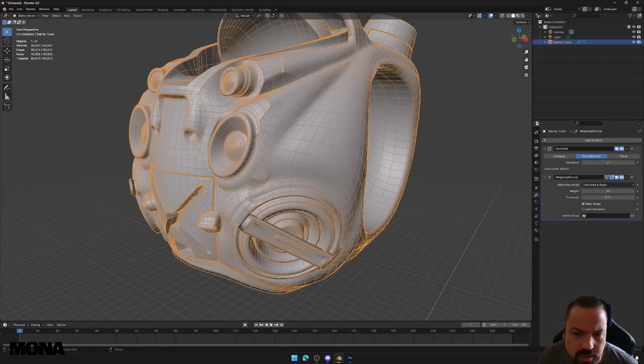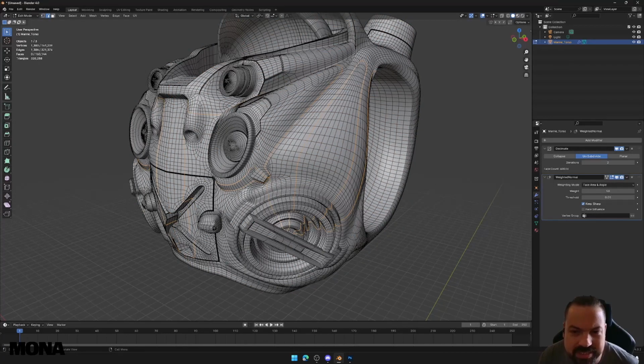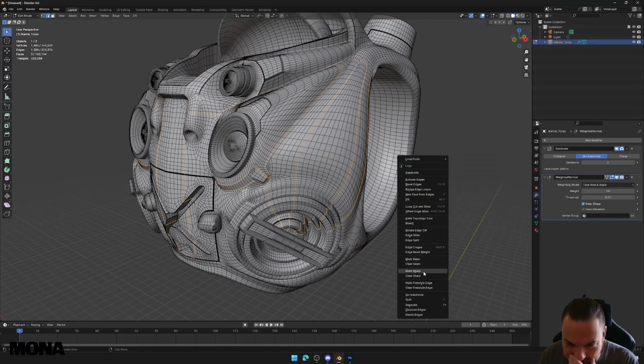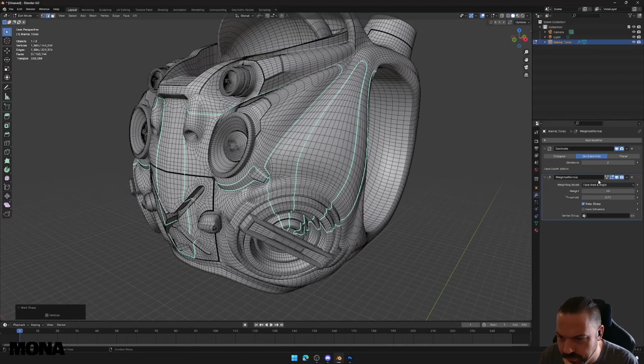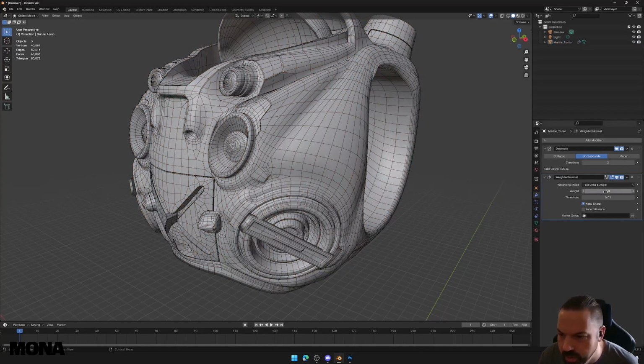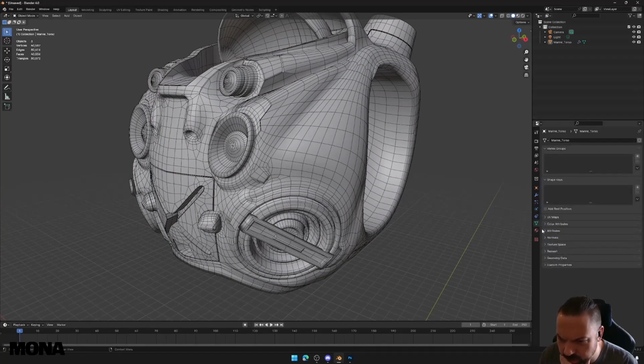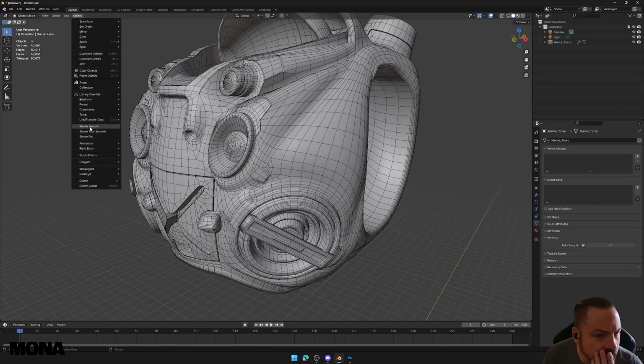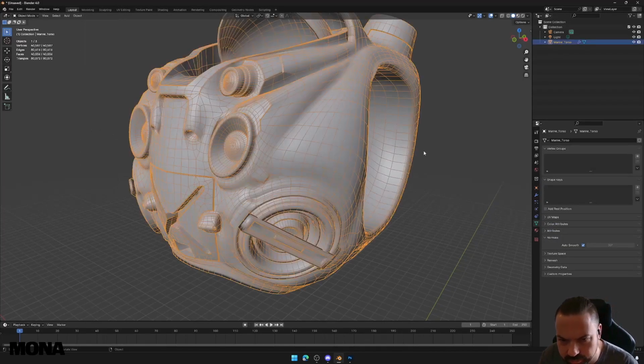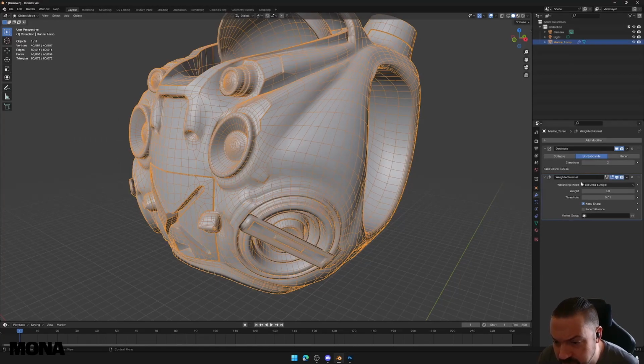Say I wanted that line to be a crease, you can kind of do that. Usually for that to work you have to turn on normals auto smooth and object shade smooth, but because of these, maybe not. So you can adjust that, and weighted normal is very useful.